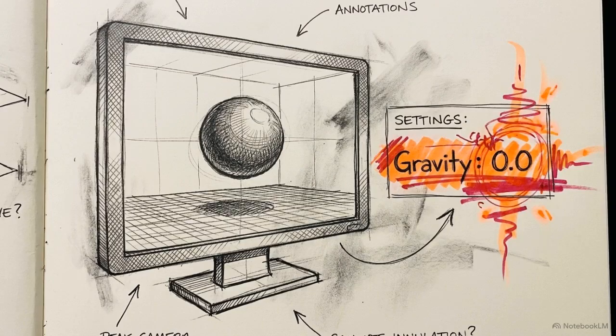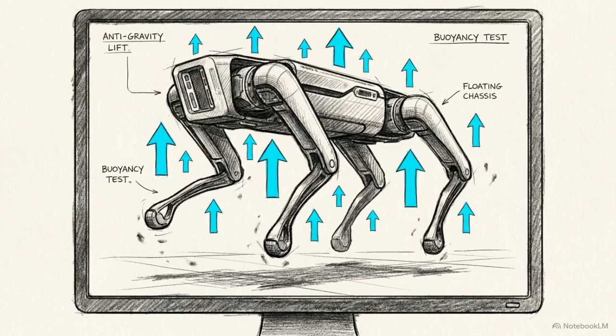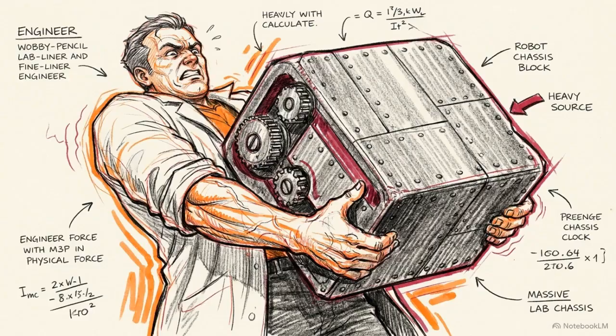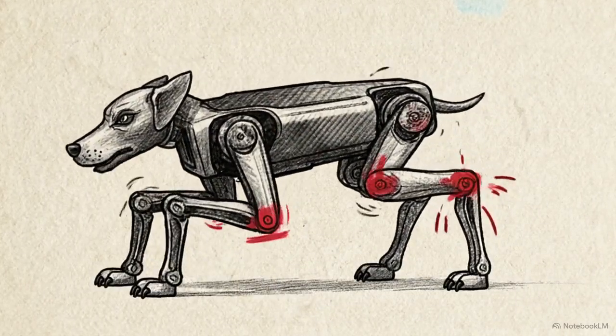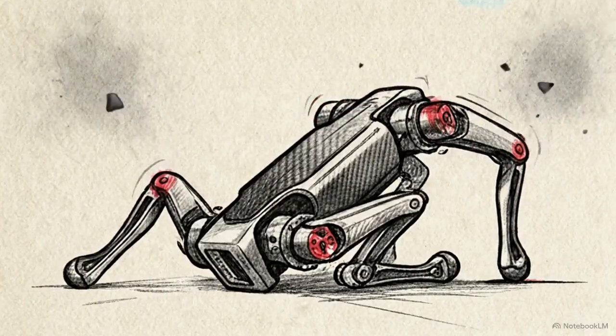The other common simulation cheat involves gravity. If you accidentally mismatch the simulated mass of your robot or reduce the virtual gravity, you are training the controller for a lighter world. In a low-gravity simulation, your servos don't have to fight to hold the leg horizontal. The controller never learns to compensate for the actual weight of hardware. These shortcuts ensure that when you place the robot on real ground, the legs will sag and buckle under the actual weight of the machine.